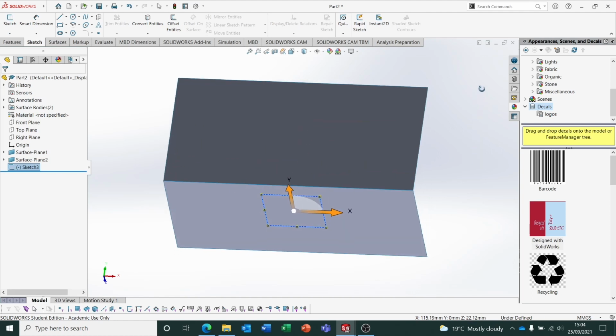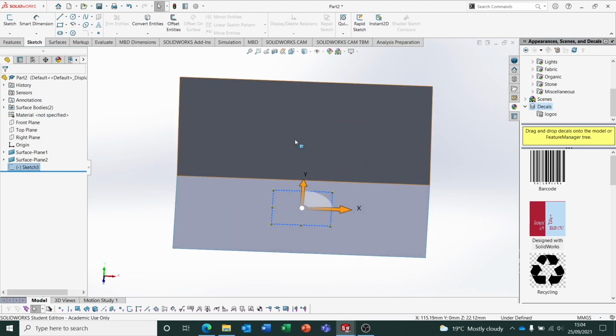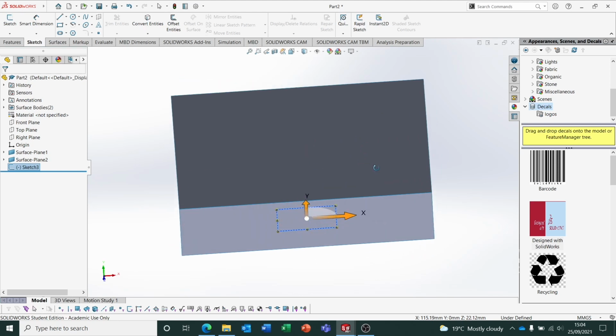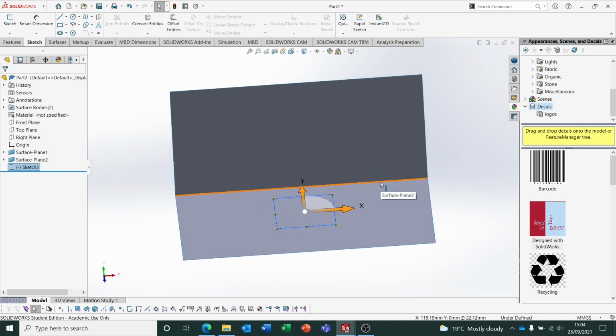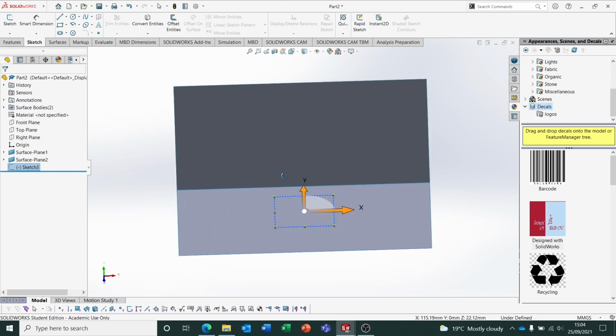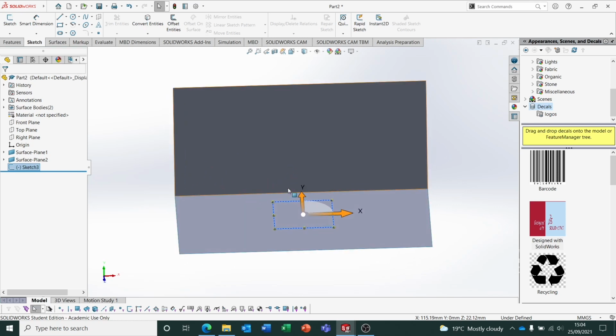What we're going to do is a loft. So we're going to create a point on a plane, a distance above that. Now the distance doesn't really matter. You can change the distance to suit yourself, or you can use the same one I do. It really doesn't matter.